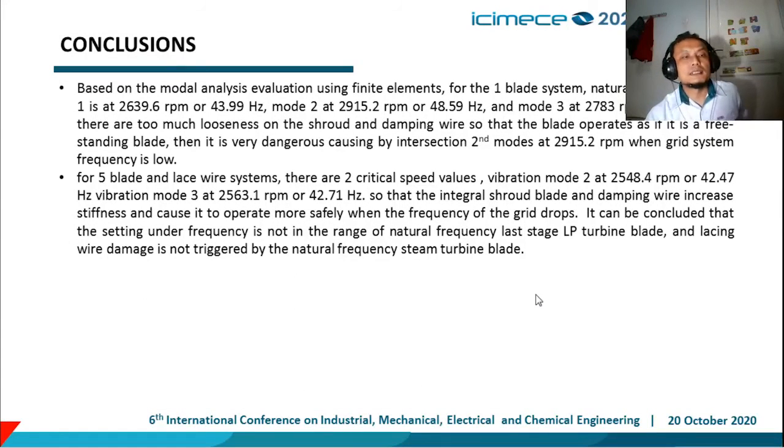So the conclusion is, based on the modal analysis evaluation using finite element for the 1 blade system, natural frequency mode 1 is at 2639.6 RPM or 43.99 Hz. Mode 2 is at 2915.2 RPM or 48.59 Hz, and mode 3 at 2783 RPM or 46.38 Hz.